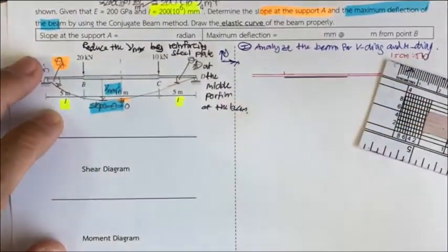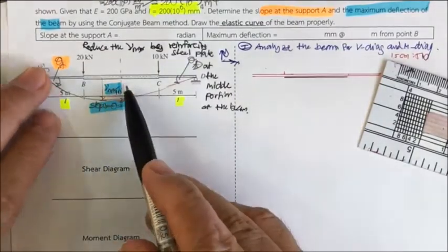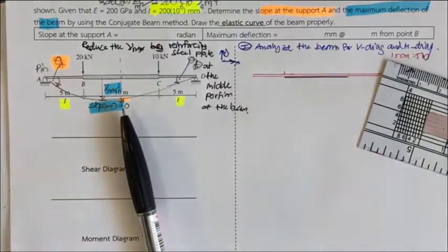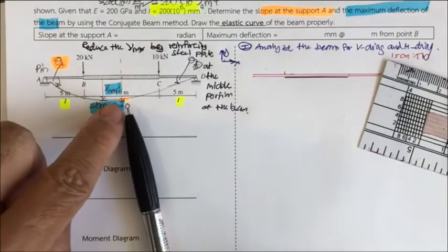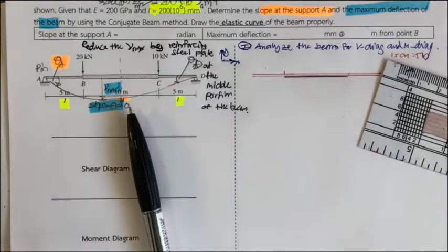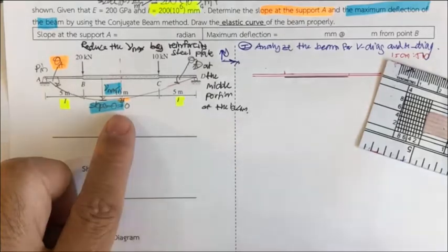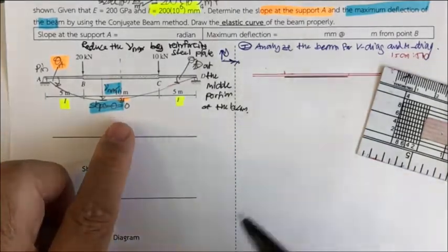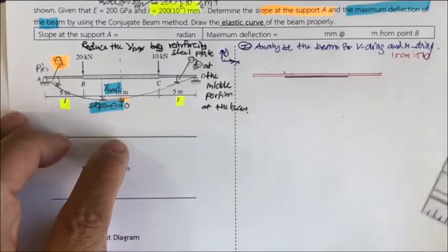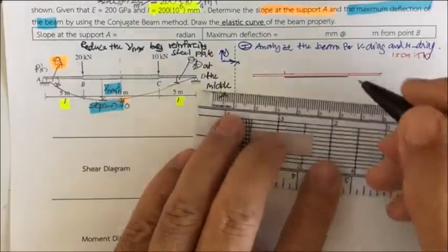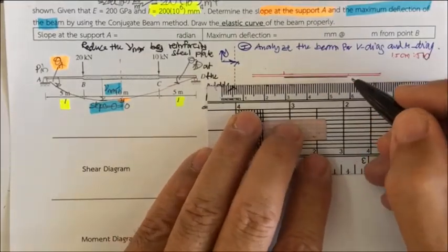This is some kind of situation. If you change this problem by taking the 2I into I, you can determine the Vmax also. And if you compare the Vmax from that to the Vmax from this, you will see that the Vmax calculated from this only one I is going to be larger than this. This is one example of how you may strengthen the beam by reinforcing it with a kind of steel plate.